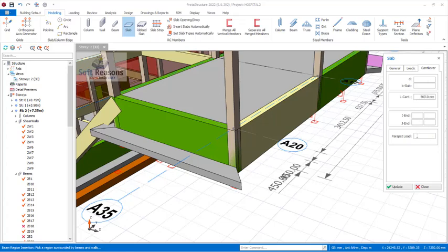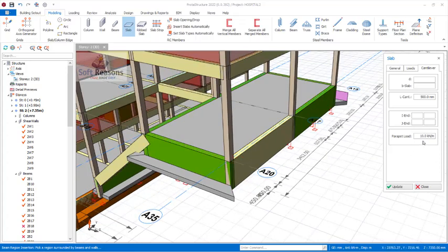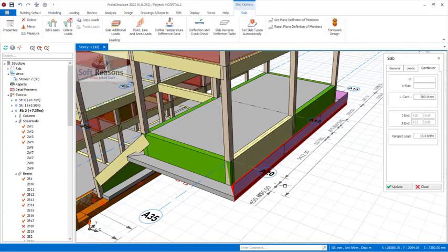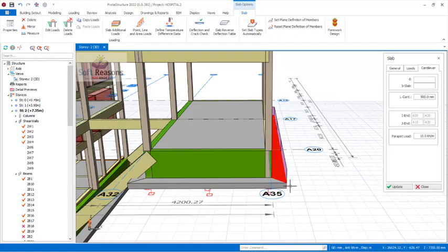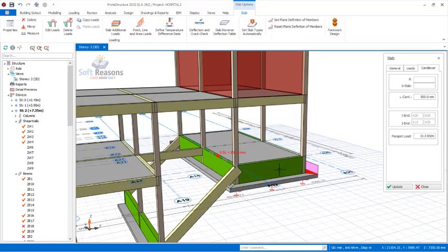We wouldn't want to apply the parapet loading. Parapet can be the soil that is on the slab, the soil that rested on top of the slab, so you can quantify that, and then you can get that to be 10 kilonewton. If you have that to be 10 kilonewton, what you just have to do, you key it in right there, and then pick the first point right there all the way to this other point, pick it, bring your hands up outward and place that. So now you can see we are having the load. This serves as the soil weight on top of this slab successfully, which we are supposed to do all around the slab to be able to apply it and carry out your design in a proper way.